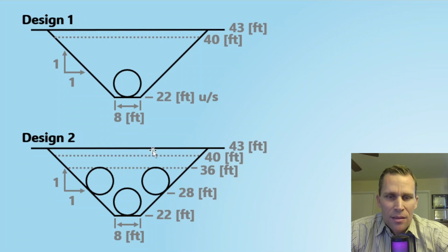The reason why I'm not putting it directly on top of the first culvert barrel is because that would result in less cover. So even though the cover is at least 3, we could go up to 40 feet here. I think it's a better design decision to try to maximize the cover if possible. So that's why I'm sneaking in these two 8-foot diameter culverts below the what would be 30-foot invert, which is the top of this lower culvert barrel, by just kind of putting them on the sides and then lowering the elevation a little bit, if that makes sense.